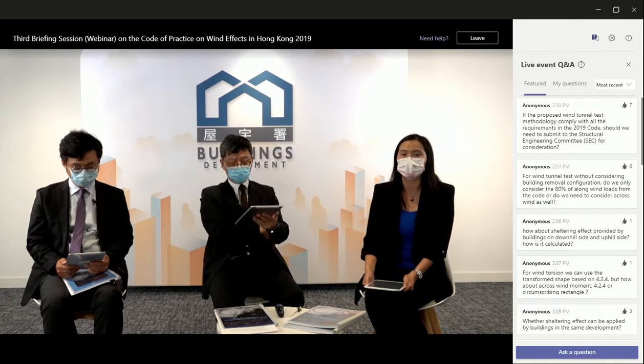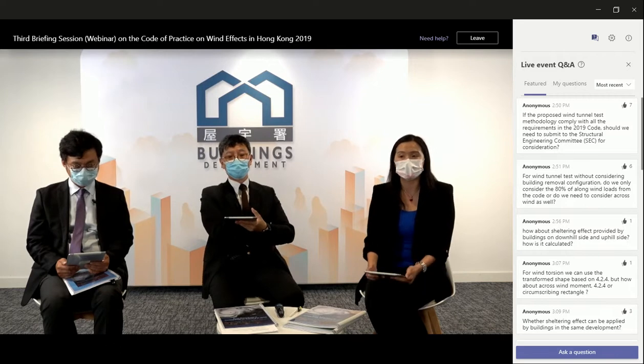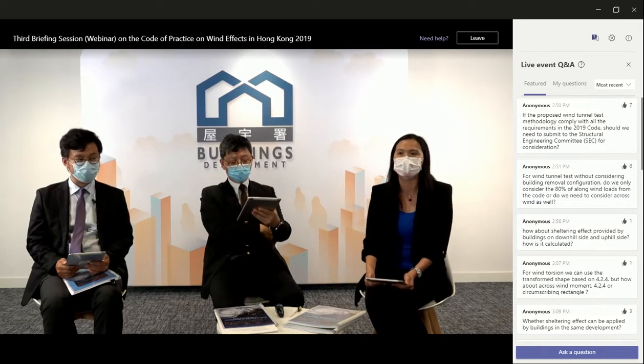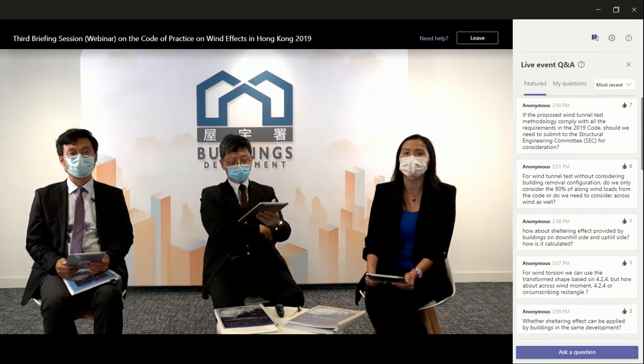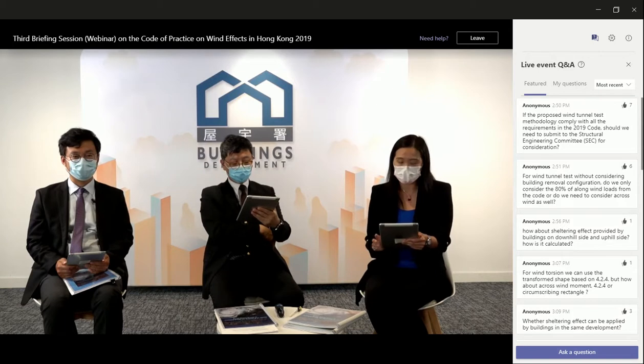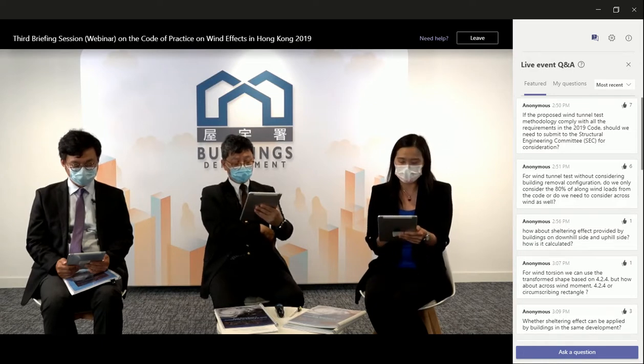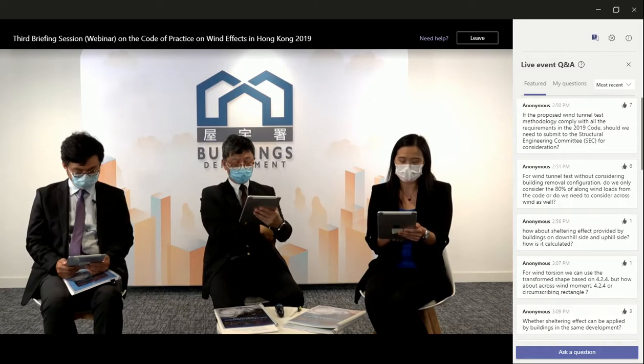So the other adjustment factor actually means the further reduction by the directionality factor and the sheltering effects. Remember, 37% of the wind pressure is already a very big discount. So further discounts due to directionality and sheltering are not allowed in this case. But remember, designers need to use the topographic factor and the size factor in this respect. Yes, okay, the next one.